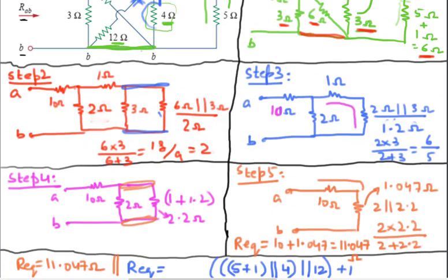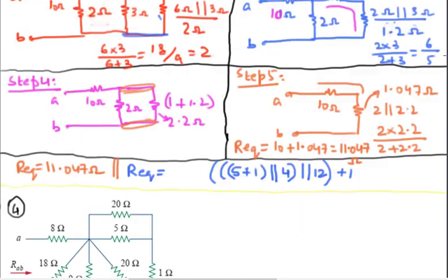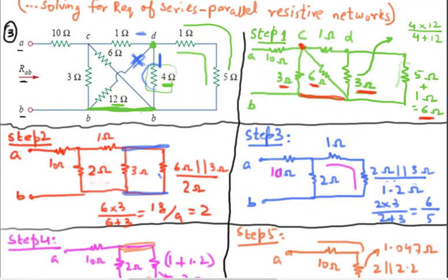What's happening next? You can see that after that reduction, you are just going to have one resistance over here in place of 1 ohm and 4 ohm, and that one is in parallel with 6 ohms. So let me go to the expression again. The whole thing is in parallel with 6 ohms. And finally, not finally, I think there is one more step.